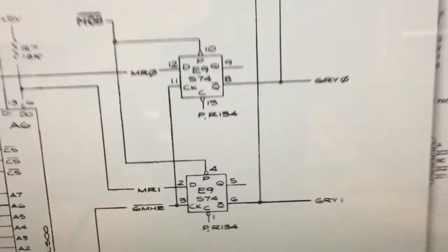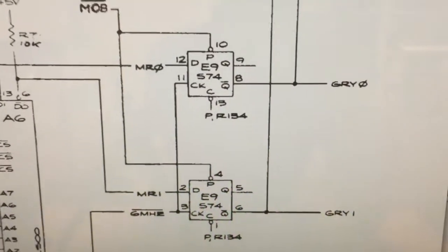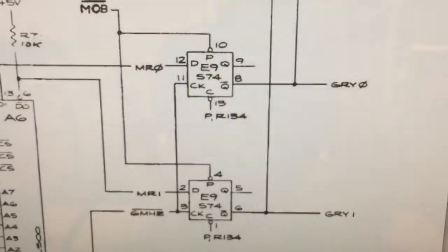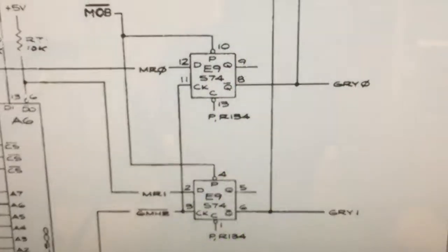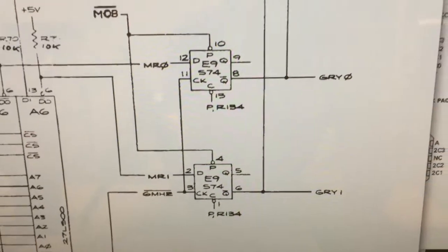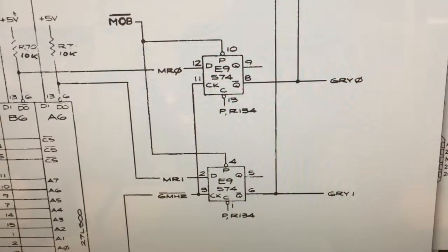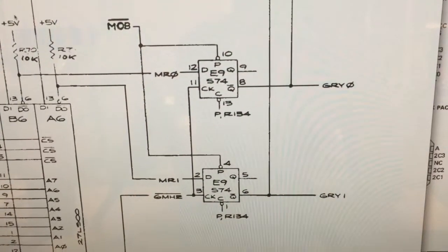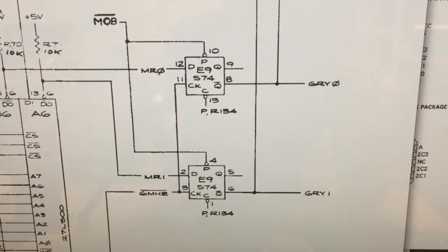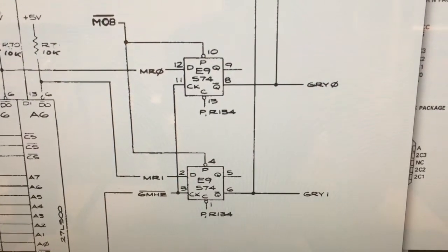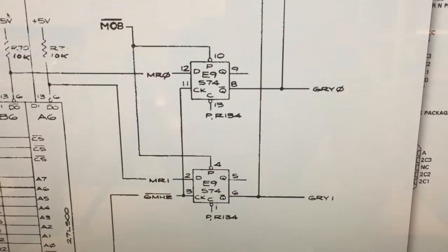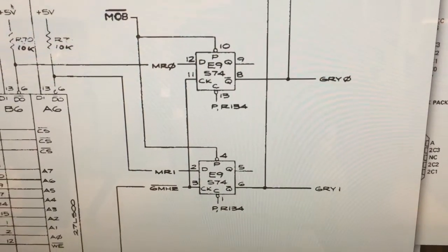Well, so I guess it is very likely that the flip-flop chip isn't working right. We could actually prove this if we attached a logic analyzer, but all the inputs seem to contain signals that are making perfect sense.